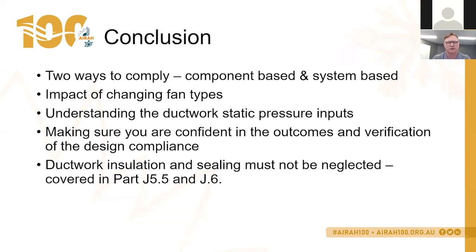What I mean is if you've got a dedicated outdoor air system connected to the VRF system, then you've got fan compliance on the ductwork and the ducted system for the dedicated outside air. So it just depends on how you've designed your total system.